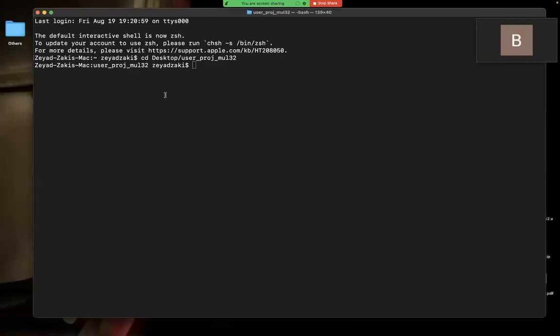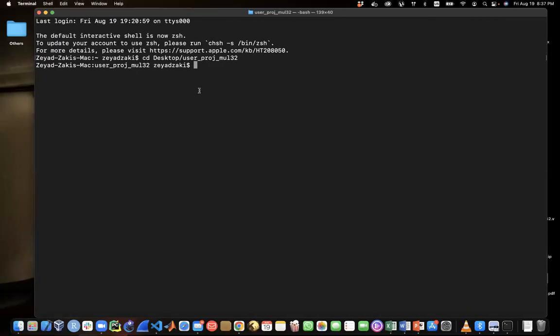Okay, so since I've opened up my terminal for the first time, I have to export my OpenLane route, and that will be inside my current working directory under the dependencies folder, under the folder I named OpenLane_source.